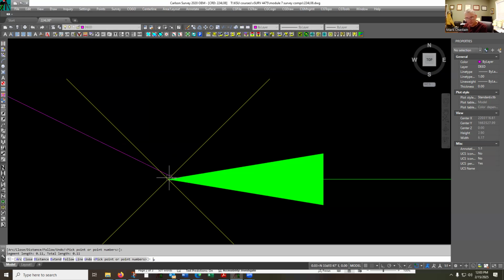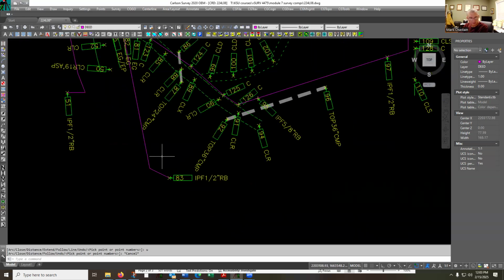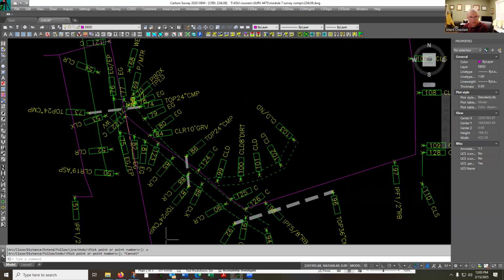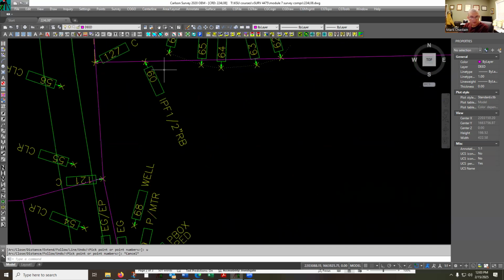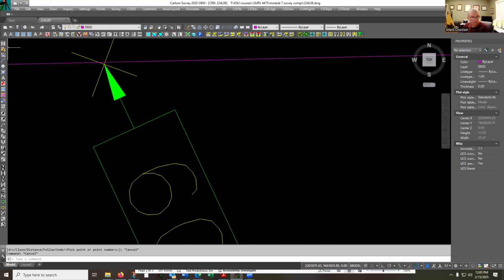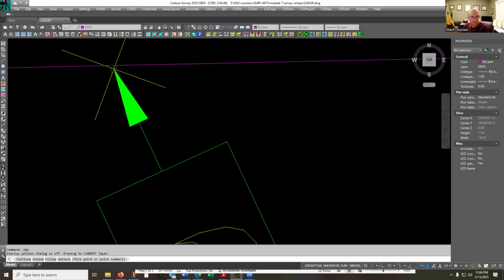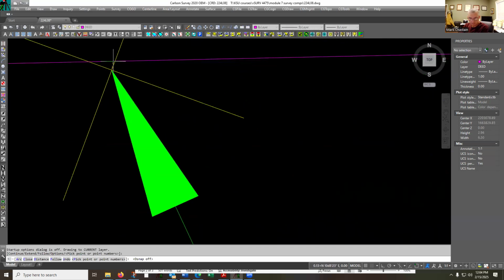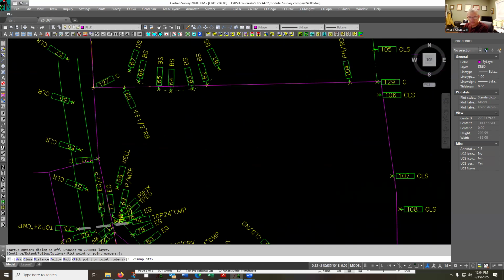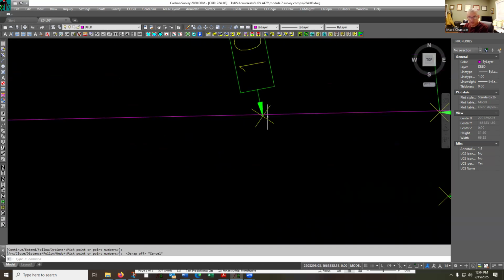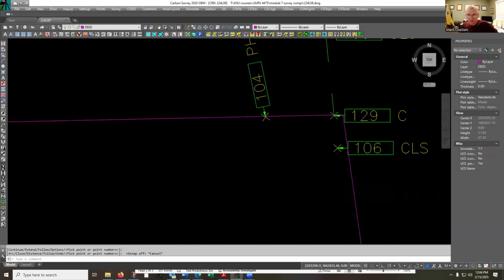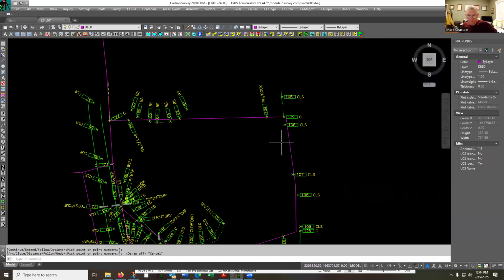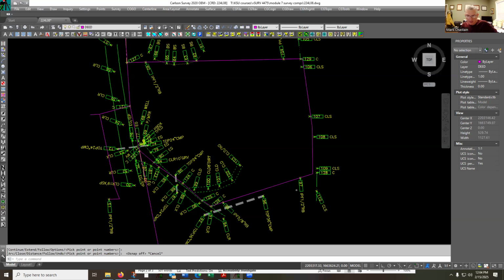I'm 11 hundredths just out of position from 51 to 83. Now I'm even better with my original number 60. It's only 13 hundredths offline now. We found a marked punch hole in a rock outcropping on the bluff going down to this creek. So, I'm liking this pretty good.